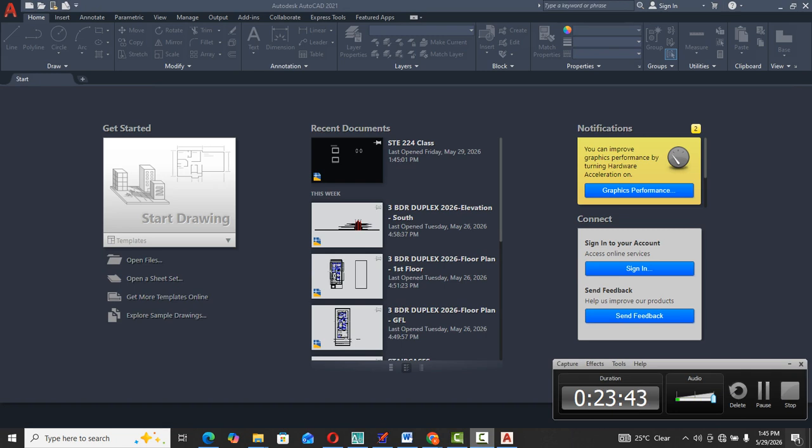I can be rolling my mouse, but if I find it difficult, it's still stiff. I can use what is called zoom: I'll type Z, enter, then A, which is zoom all. I click enter, so it has zoomed all, to show all the drawings. If there are many drawings, I will start seeing where the problem comes, when I have many drawings on this page and the zoom is misbehaving. If I zoom all, it will zoom everything and show me everything in the drawing.